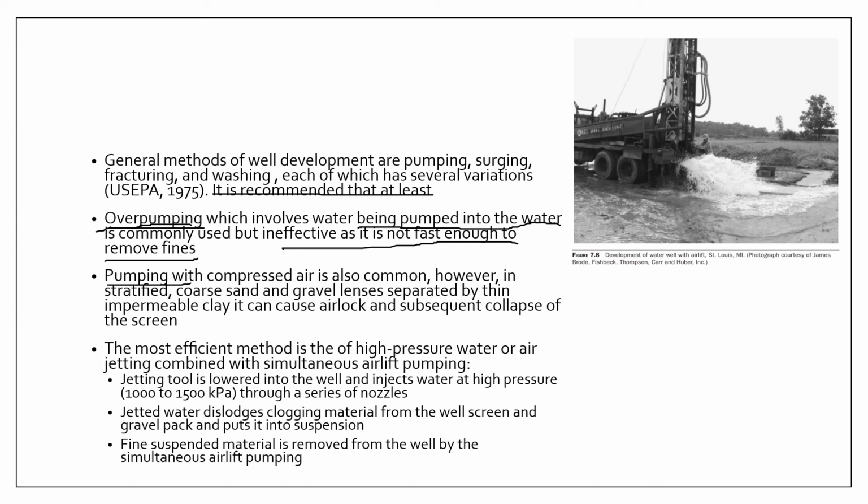Now, another method that is common is pumping using compressed air. All right, so what they do is they try to inject compressed air into the formation. Although the problem here is that pumping in compressed air, especially when you are dealing with stratified aquifers that contain impermeable clays, can actually cause an airlock, and this can cause your formation to collapse.